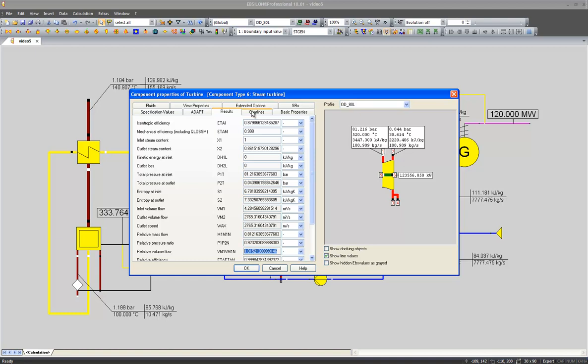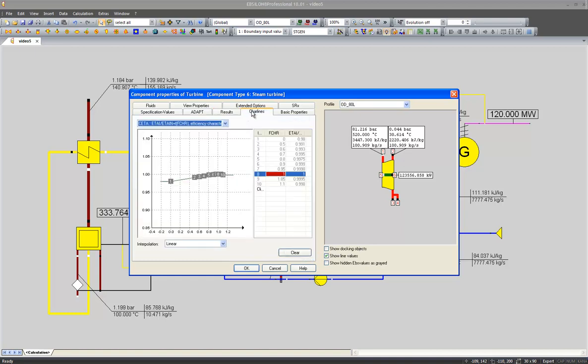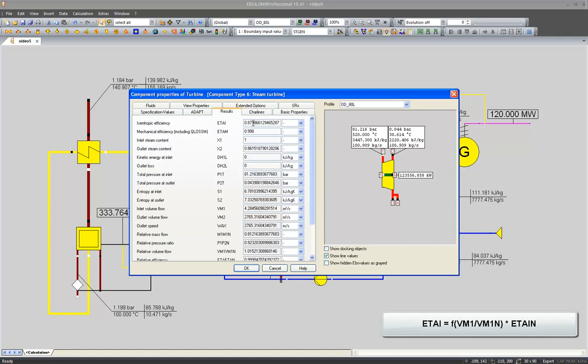And if I look at my characteristic line again, I will see that we are somewhere in between those 2 points. And of course, if I interpolate between 1 and 0.995, there will be a value smaller than 1 that I have to multiply with my nominal value in order to get my actual efficiency, which is right now exactly 87.99% and not 88 anymore.